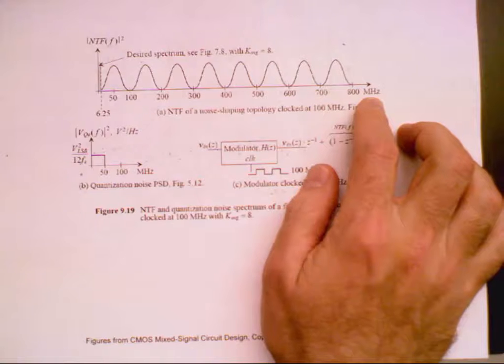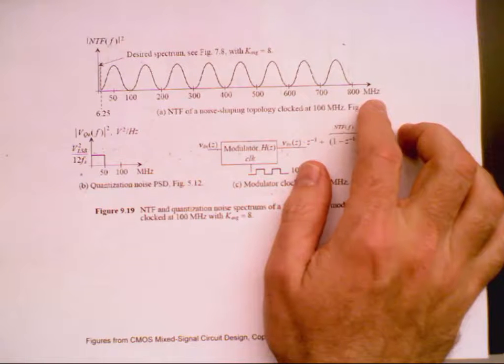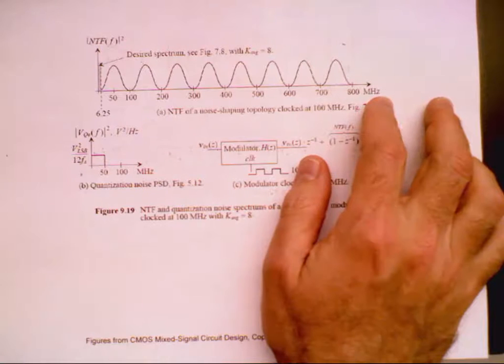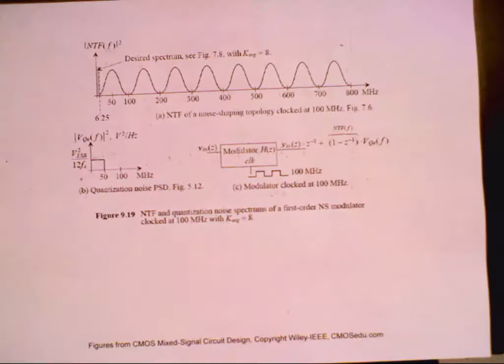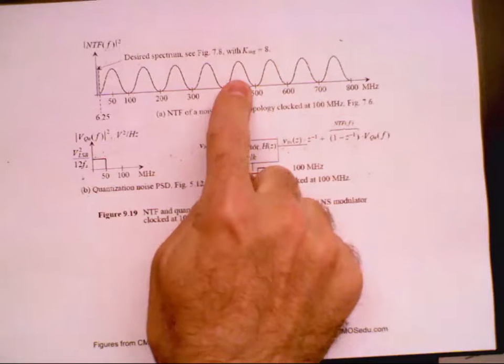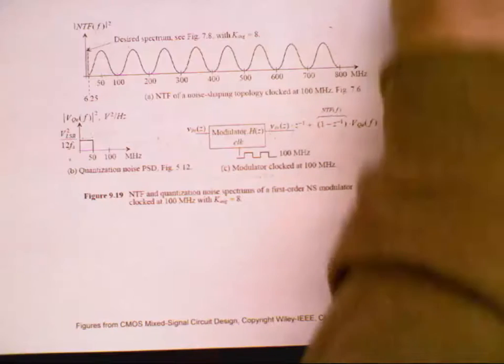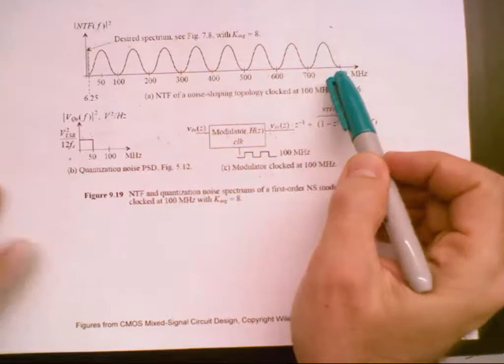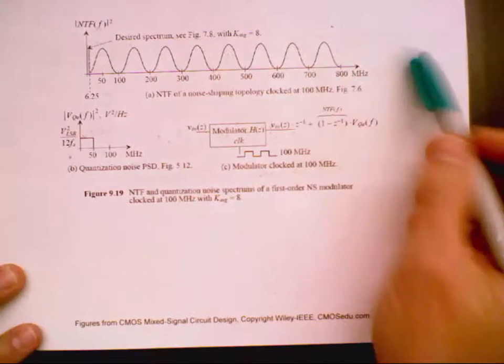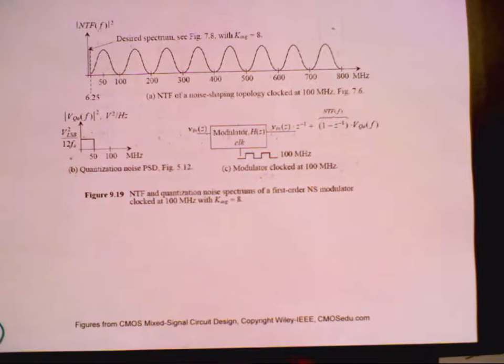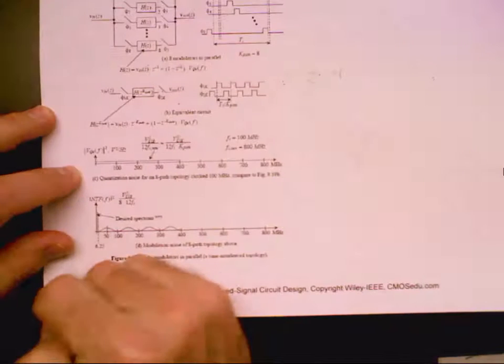Yeah, it's a sampled system. It's a trivial question. It's a sampled system. Any sampled system's frequency response repeats at intervals of f sub s. I hope we went through the unit circle enough times. We're rotating around and around and around. Everything repeats, right? So that's what we're seeing here. We're starting out with a single modulator showing the spectrum out to 800 megahertz, but it doesn't actually stop. It keeps going, repeats. Any questions on that? Why? Well, we're just rotating around the unit circle. Okay, so what happens if I say, let's try to improve speed by putting the modulators in parallel.